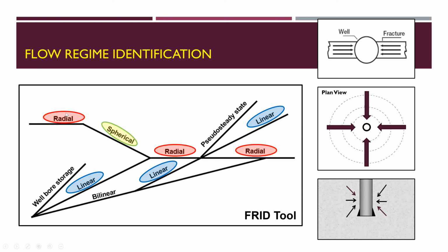So I will take it in the reverse direction. From the pressure interpretation we have, if we see this trend here, it tells us that this trend is representing linear flow. However, this trend, the flat one, is representing radial flow, and this trend is representing spherical flow. This is why we are studying the flow regimes and how to represent them in terms of derivative. Derivative will be explained later.